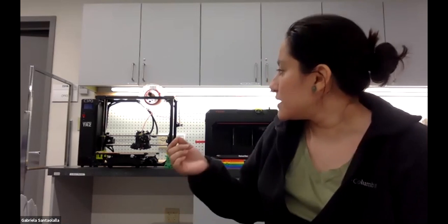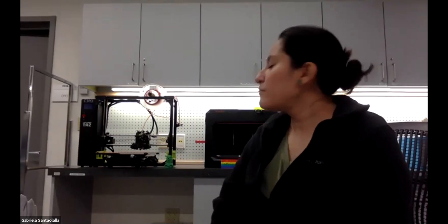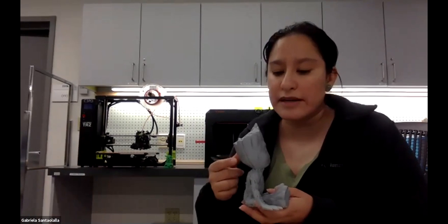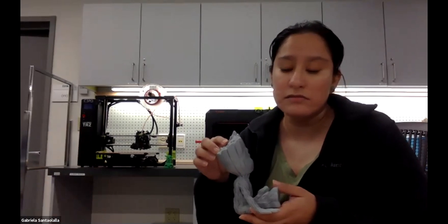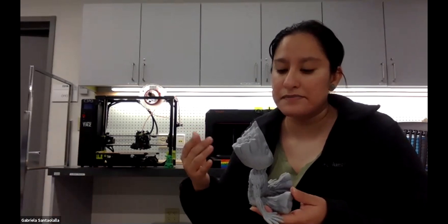The printing overall is also limited by a few different factors. There's print speed, the diameter of the nozzle, as well as the layer thickness. And most of the printers here have different nozzles that you can install onto the printer, depending on what it is that you're looking to print. But there are obviously other factors too. So this is purely decorative. You're not able to notice, but inside it's entirely hollow in order to speed up the printing process.